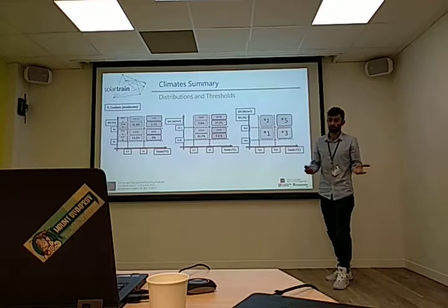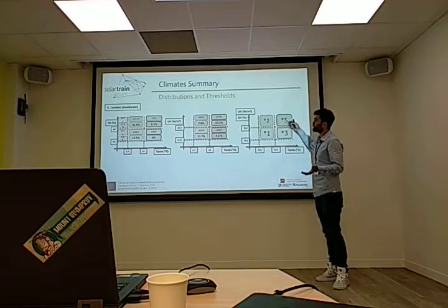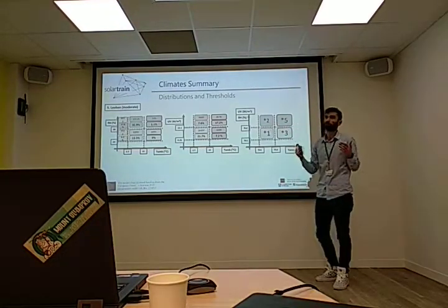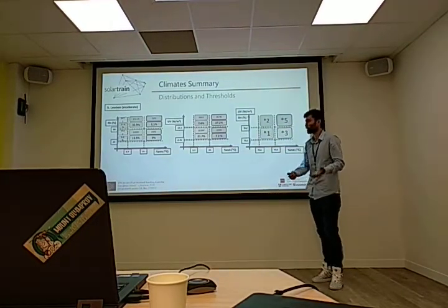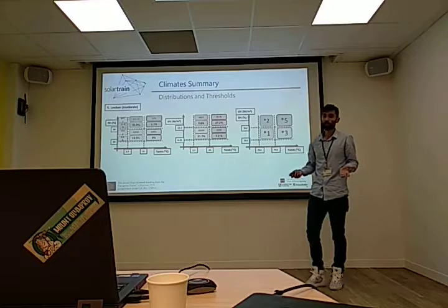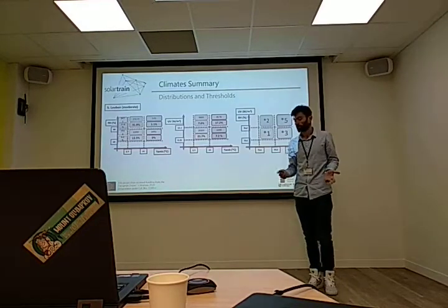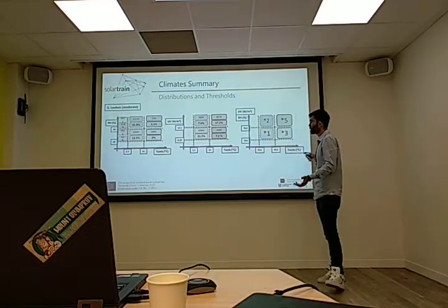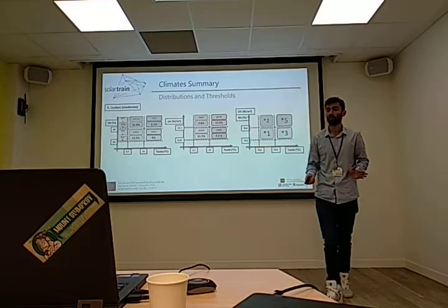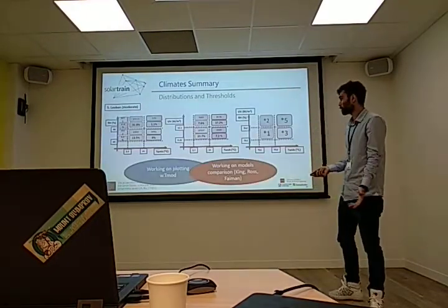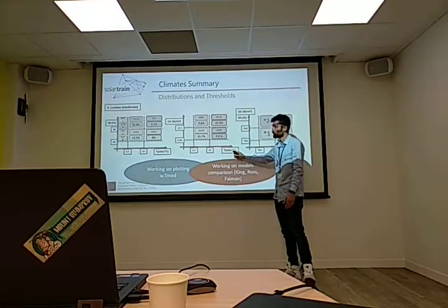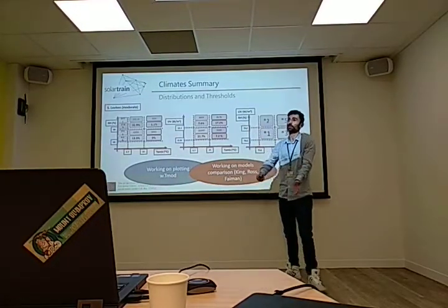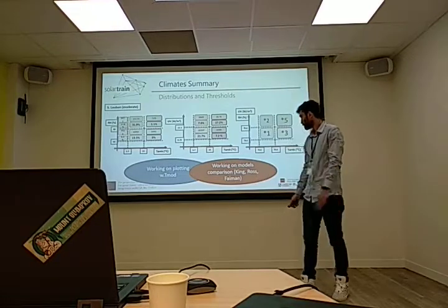When the module is found in this area, the degradation factor should be higher than when it is in these milder conditions. However, these thresholds so far are set arbitrarily, and with ambient temperature it still doesn't make any sense. So the next step would be to have graphs with module temperatures, which will make more sense for an analysis closer to degradation.